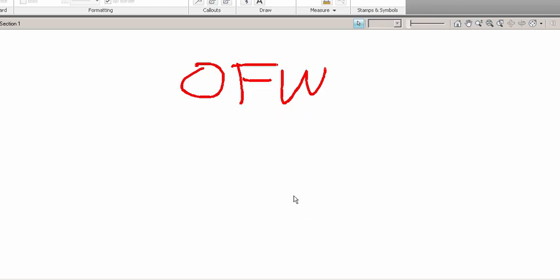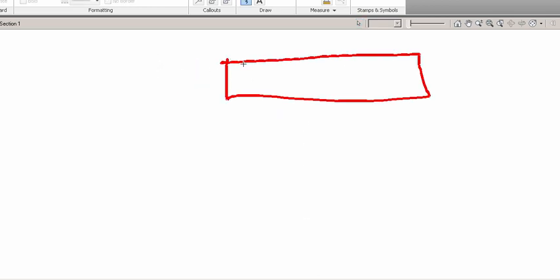And there are some limits though to the process in the fact that you can't just take a big slab of metal and be able to effectively work with a torch. Typically a 1/4 inch or less is what you're going to look for in terms of applications with a torch. Doesn't mean we haven't gone thicker with it, but this is sort of the thickness that we can work with fairly easily.